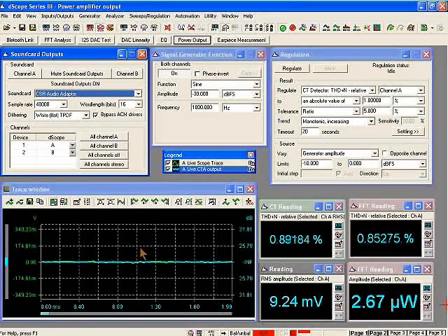Alright, so what I want to do is to find the point at which my power amplifier can deliver no more useful output power. In other words, the onset of clipping distortion, where the output voltage of the amplifier starts to clamp to the supply voltage rails, and we simply can't generate any more useful output amplitude swing.